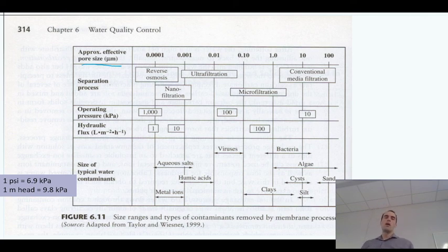This water is very small. There are some other issues. Actually, the space station has some issues with very, very small levels of methanol and ethanol being formed just from biological processes that occur in their water system, and their membrane filtration systems can't remove it because it's so close to the same size as water that even though they're using reverse osmosis, it's just passing right through. So there are some interesting investigations on how to prevent the accumulation of ethanol in their drinking water. It would be an odd thing to think about, but there are some processes where you might get a little formation over time.